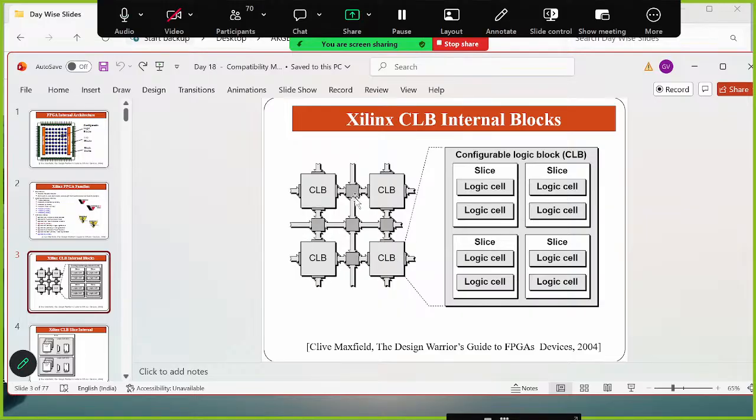This small gray box you can see is termed the switching matrix, where the CLB's wires are configured and connected to another CLB's wires. It is just like your electrical wires are routed, and in between you can put some switch or connector, so that you can connect one set of wires to another set of wires, so that you can route the data to another house. It is the same thing over here.